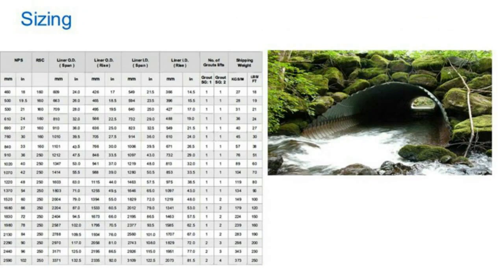If you need to ovalize a Weholite pipe, as I mentioned earlier, we can do ovalization and provide assistance with ovalized dimensions. Our literature provides charts showing dimensions of the pipe that's been ovalized to 20%. Obviously, you can do 5%, 10%, or somewhere up to there. But should you need something that's more than 20%, you need to contact your Uponor representative to confirm suitability of the application. And keep in mind that these are 20% from the OD, or OD dimensions.